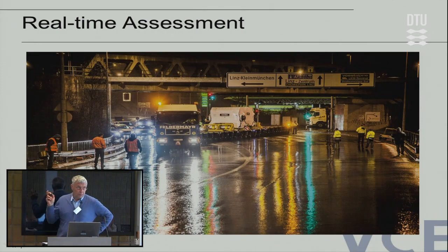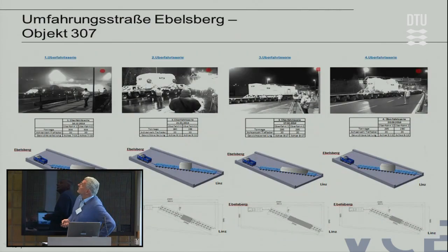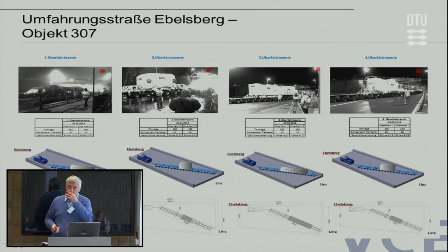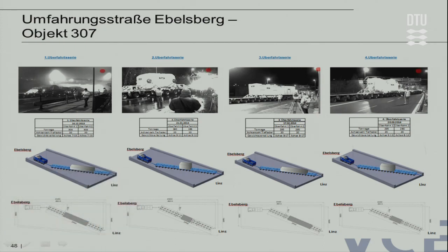We made 5 measurement campaigns, one before, and then always 2 trucks per night, and tried to find out how it works. So the individual pieces are shown here. It is going in the skew direction to hit all the main beams. And the objective was also very simple, to say, is there any damage after this load which goes far beyond the codes? And if you do a computer model, you're not able to show that this is safe.